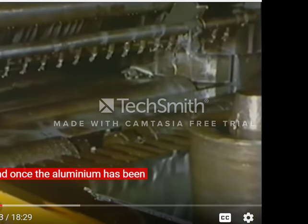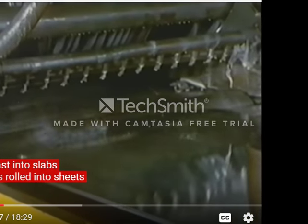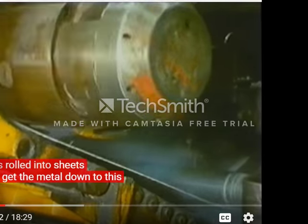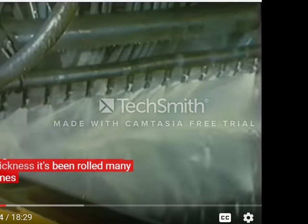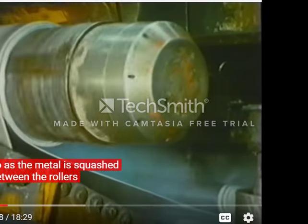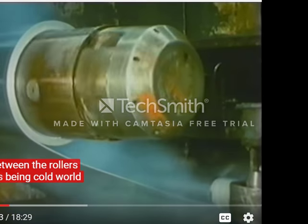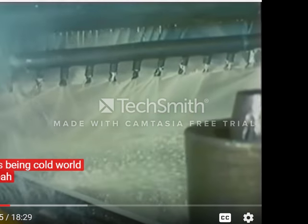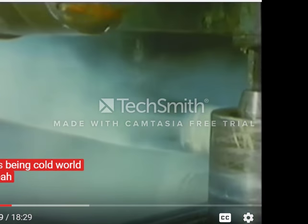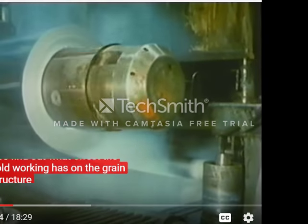Now, once the aluminium's been cast into slabs, it's rolled into sheets. To get the metal down to this thickness, it's been rolled many times. It's now relatively cold, so as the metal is squashed between the rollers, it's being cold worked. Let's find out what effect the cold working has on the grain structure of the aluminium.